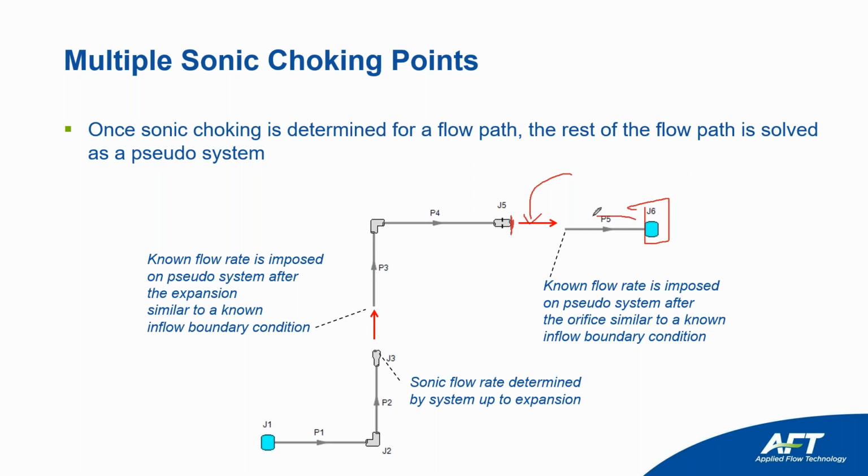So we start working our way back up, calculating what the pressures and flow rates and temperatures would be up to this point right here, which is downstream of the choke, and then we can keep working our way backwards. It is highly iterative, very much so, to ensure that the mass and energy and momentum is balancing all throughout the network there. But that's how Arrow is doing it inside the solver.